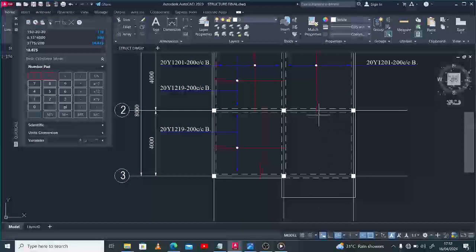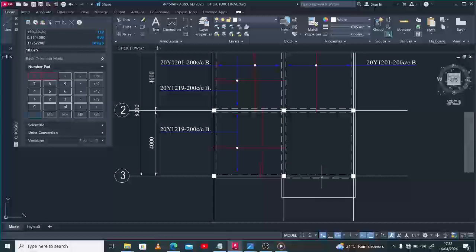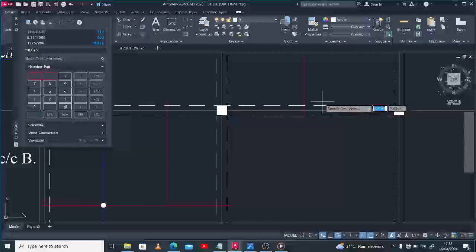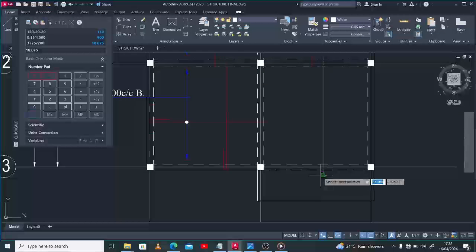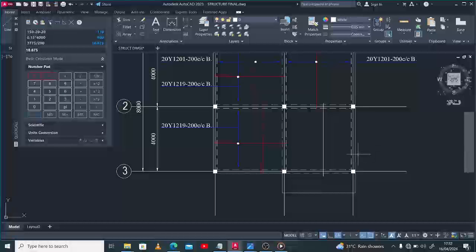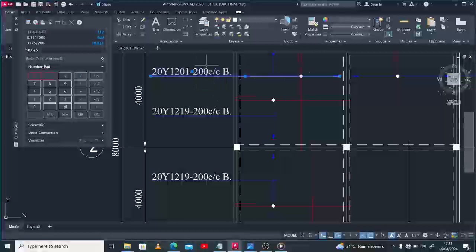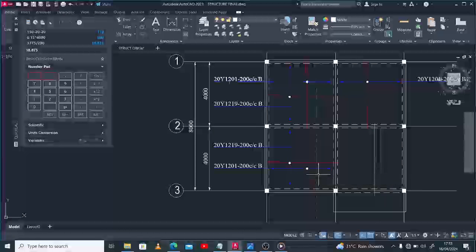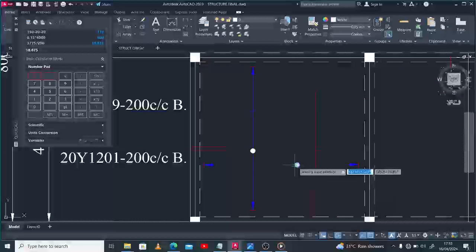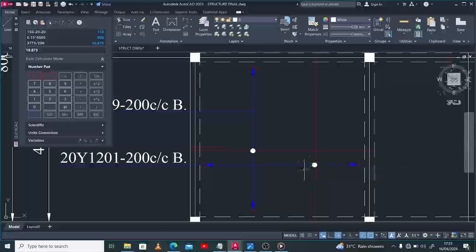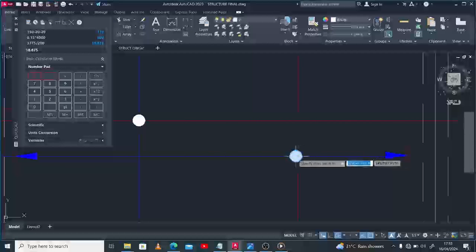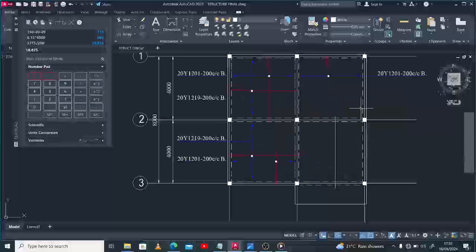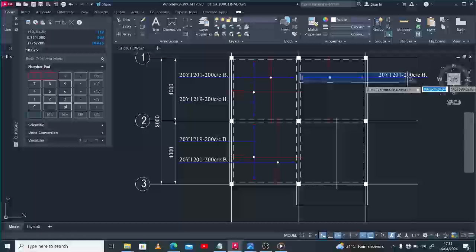Now, on this side is going to be a different case because this is not the restrained end support, it is a continuous support, or a cantilever support rather. So your reinforcement is going to span like this without an anchorage because it's still within the slab. Now, the calling out of this reinforcement will be such that this comes here separately but points to this reinforcement, and then this also points to this reinforcement.